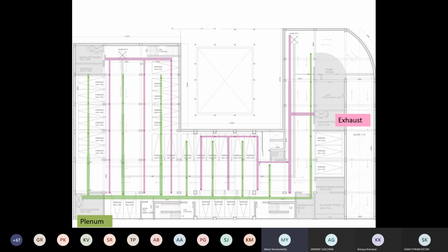So if you have two exhausts, the ventilation is automatically negative. So not only from the plenum, but also from your windows and ramps, you will feel the air coming in. Because of that equation not needing to be balanced, I can have this. I cannot have this in AC. Are we clear on this point? What I'm trying to say?